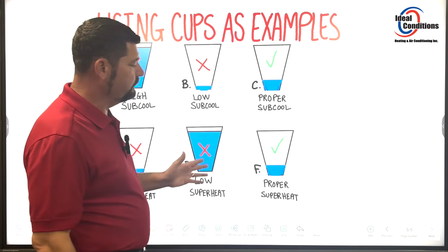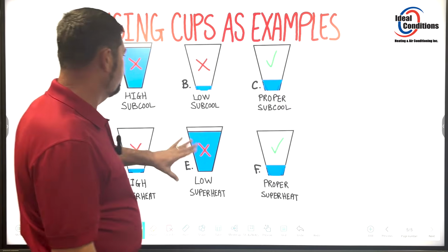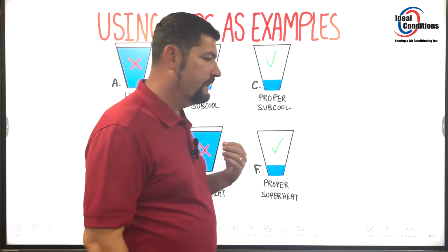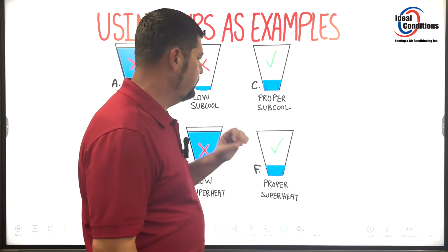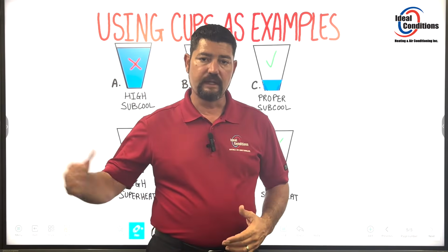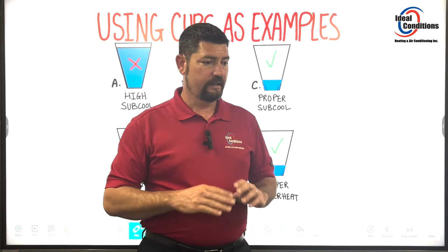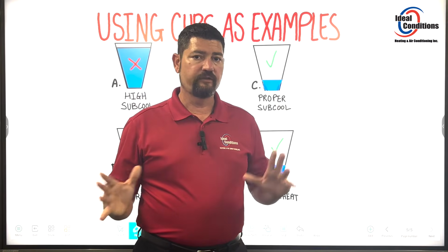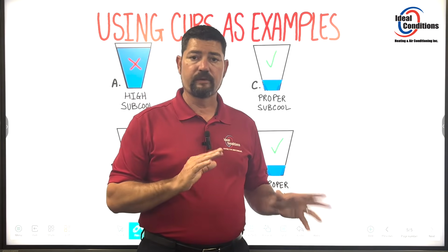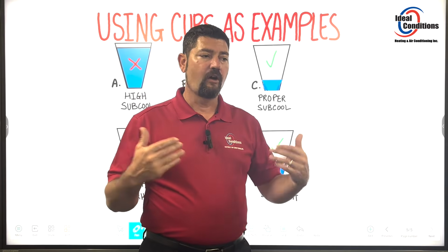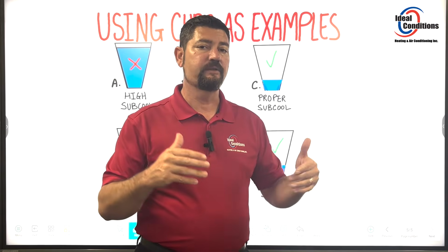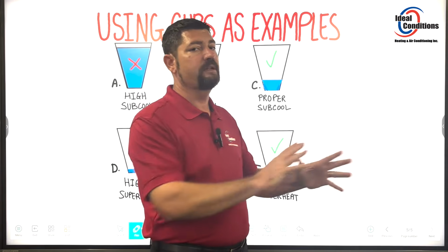So at the end of the day, what we're looking for is the proper ratios, and to achieve those proper ratios, we have got to make sure that everything is properly cleaned, that we're getting good heat transfer on our fins, that we're getting proper airflow, right? Nothing's restricted on the airflow side. All the copper pipes are the right size, metering devices are the proper sizes, and then we can begin that journey on, are these values even accurate values that I'm receiving? If they're accurate values, then we can start dictating what changes need to be made.